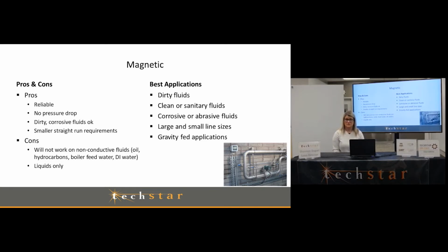And for severe service, they can come with a ceramic liner. So something that's really erosive that might eat away at other fluid technologies, a mag meter might be the best choice simply because of the materials that it can be made of. It doesn't work on oil, hydrocarbons, usually boiler feed water or DI water.